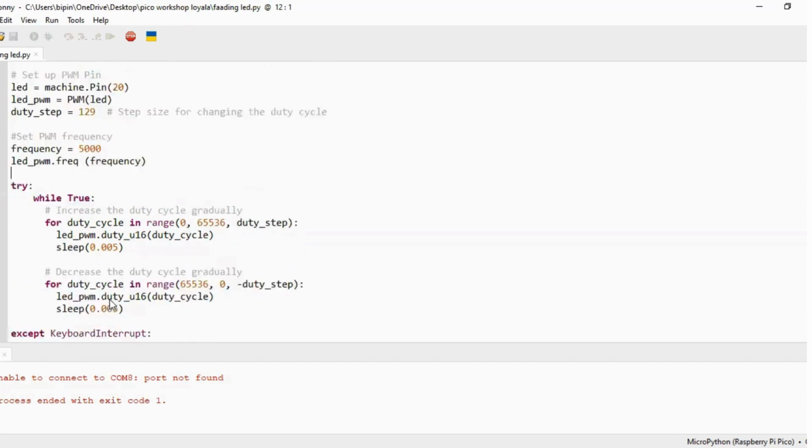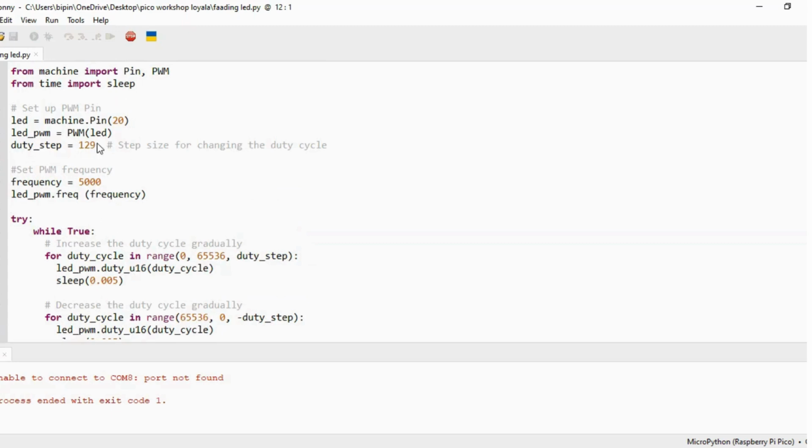You can see when a program is written. In the coming video, I will show you about these programs. Okay, so I will write a program in MicroPython. The same program I will write in C also, and we will check loading the program on the Arduino board as well as on your Raspberry Pi. Well, please remember, for the Arduino board you compulsorily have to use the Arduino IDE, but for the Pico with the MicroPython language you have to use the Thonny IDE. Okay. Next we will see some small programs which we'll try to put in C as well as in MicroPython.